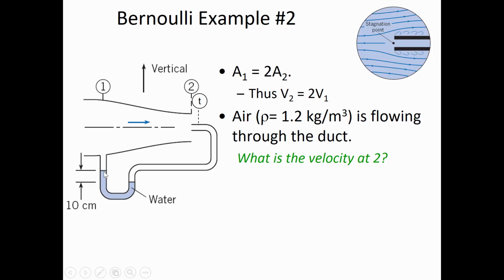So inside of this tube, conditions are static. So we'll apply Bernoulli's equation on the inside of the nozzle, and we'll use the hydrostatic equation on the inside of this stagnation tube. Okay, so the general principle is that the energy at each of the locations is conserved.